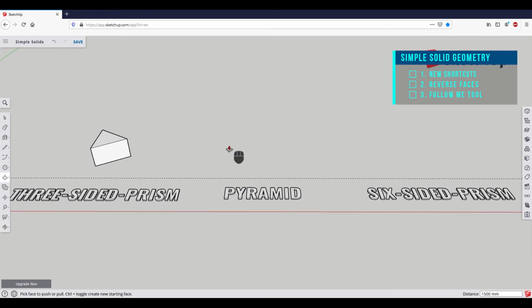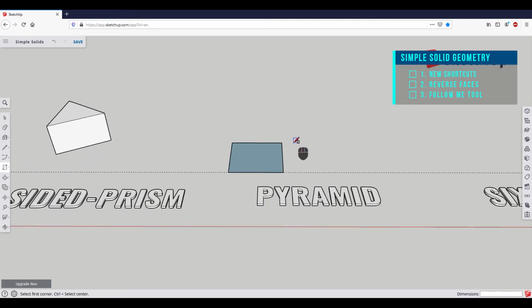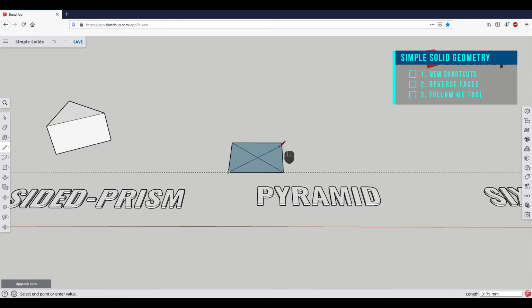The basic shape of the pyramid is a square. So select the rectangle tool by pressing the R key. Then place the starting point by left-clicking and draw the shape using the dotted line, or type in 2500, 2500 and confirm with Enter. To be able to connect all sides of the pyramid with the tip, we need to draw a straight line from the center. Select the line tool by pressing the L key, and then divide the square twice. Just like so.